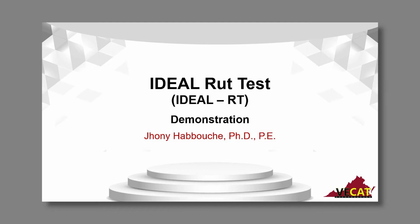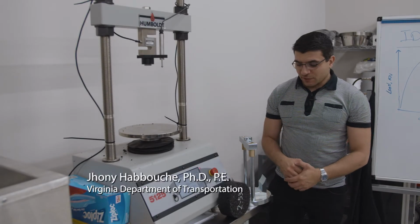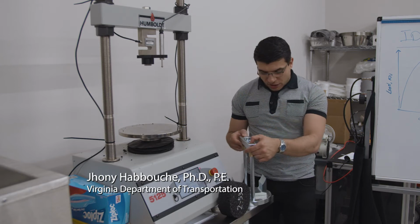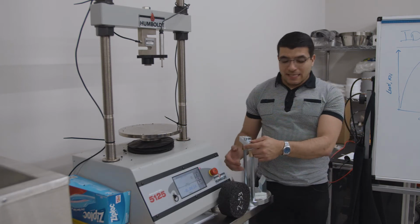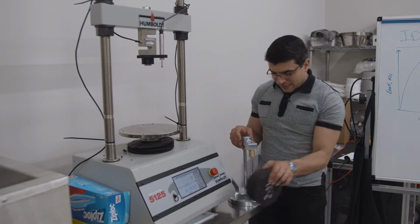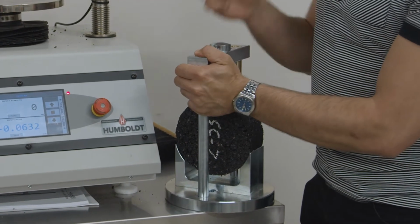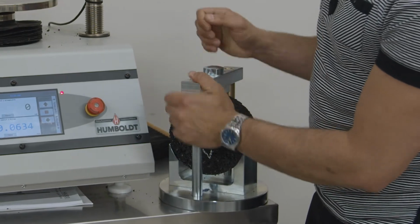Hi there. In this segment, we will show how to perform the IDEAL-RT test, or IDEAL RT, at high temperature on an asphalt mixture specimen. In this test, we will need a specific jig that has a U-shaped steel base, to which we load the specimen. We make sure the specimen is centered, and then we close the jig.